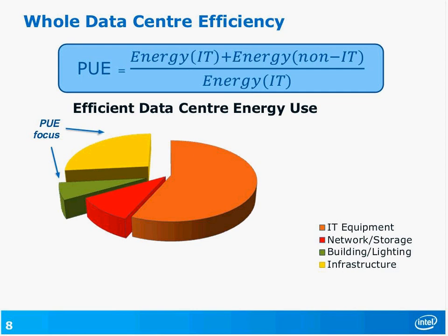When we started rolling PUE out and people started measuring it pretty extensively, we found, actually an organization called the Uptime Institute did a survey, and they found that the typical PUE was 2.5. It's about more than twice the energy that was required for the actual IT, the productive part of the data center, was coming into the data center. Fast forward 5 years to 2012. Their latest survey shows that the typical PUE is around 1.8, 1.89. So there's still a lot of room for improvement, but we are making strides.